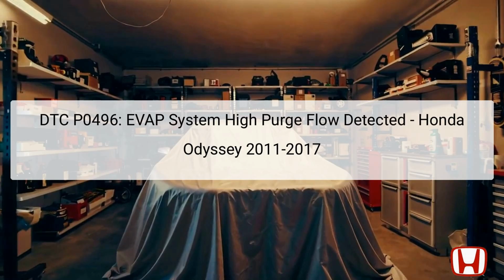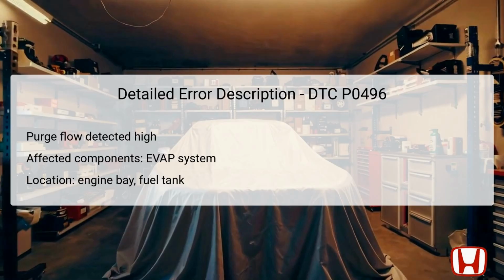It's crucial to perform a thorough diagnostic evaluation, including freeze data and onboard snapshots, before beginning any repairs to understand the context of the trouble code fully. The DTC P0496 signals an abnormal condition within the evaporative emission control system related to excess purge flow.